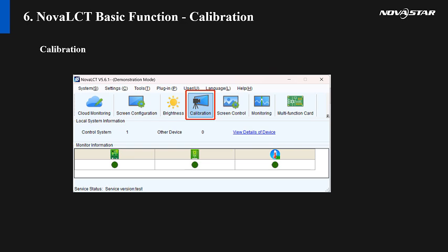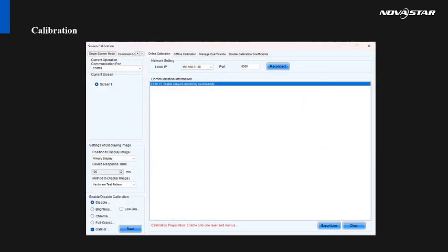Here we can see the calibration switch. We have 3 modes, and so far we have 4 calibration modes: brightness, chromaticity, full grayscale calibration, and the low grayscale calibration can be turned on and off. Online calibration: the online calibration server, in conjunction with the corresponding calibration system, can perform chromaticity calibration point by point. Offline calibration: the calibration coefficient can be manually adjusted, which is mostly used for multi-batch adjustment.